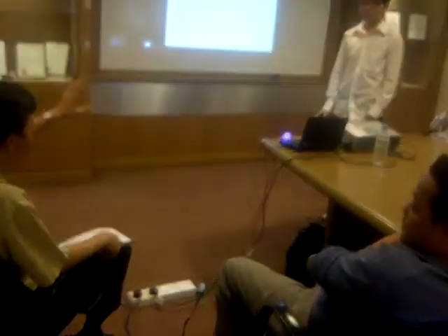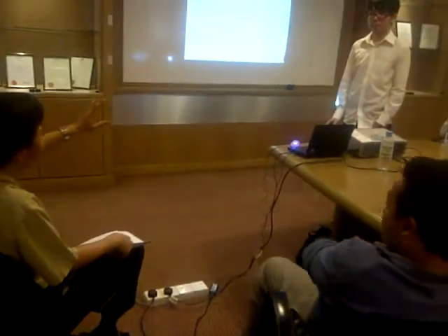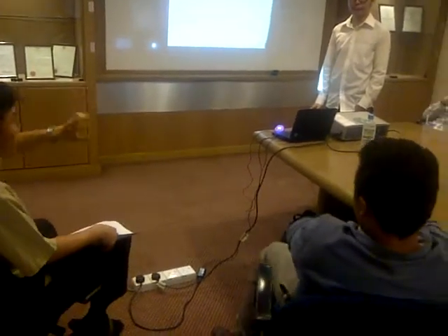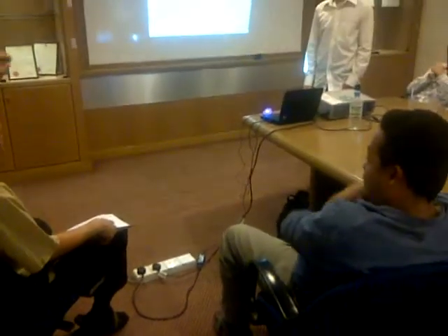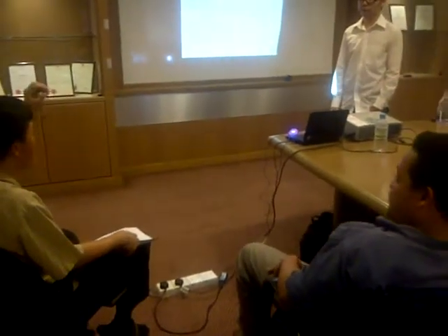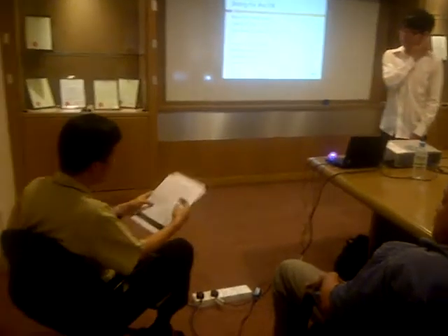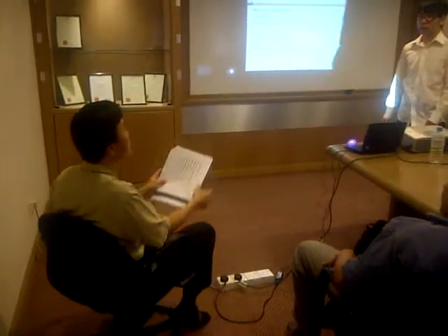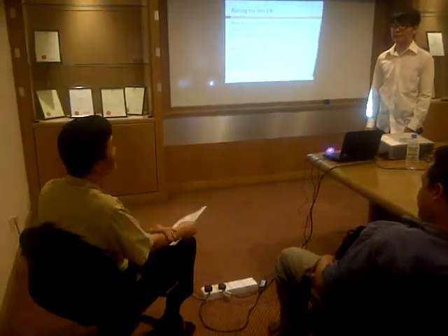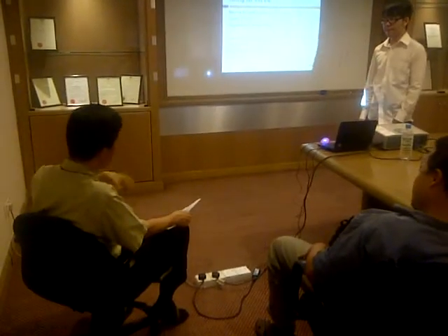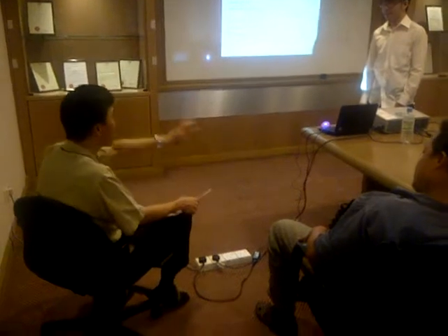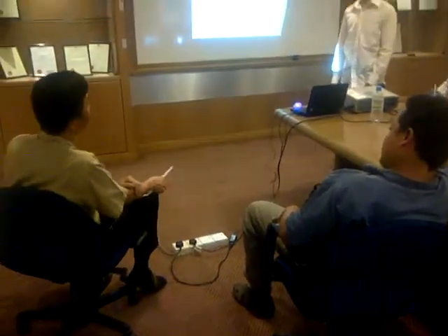I believe a normal PC will be about 100 watt, the most. But you check back the spec. What you can do is go to the internet, check the PC, and then go to Dell. The Dell catalog actually tells you the actual power consumption. From there you will know it's much less. Even if I connect a few to one socket, it will never exceed 1000 watt.